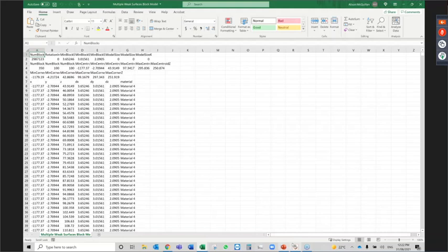Okay, back in Slide3, I'm going to select the CSV file to import. And now I need to define which rows and columns the data I want to import begin at. So the starting row in this example will be row 8.